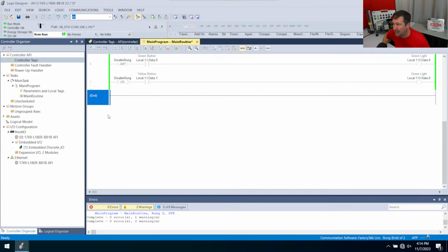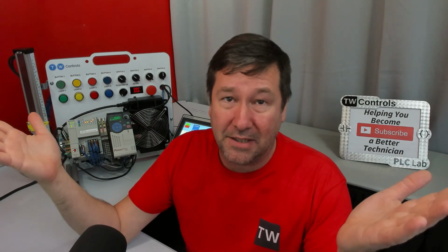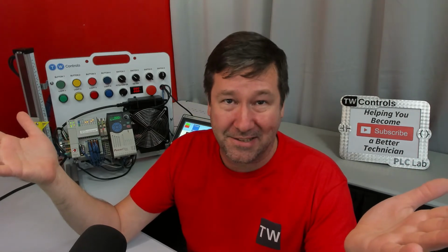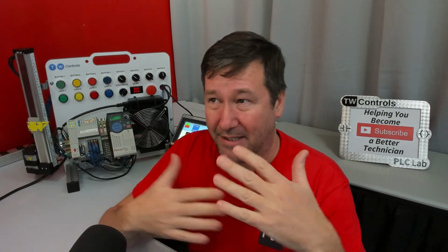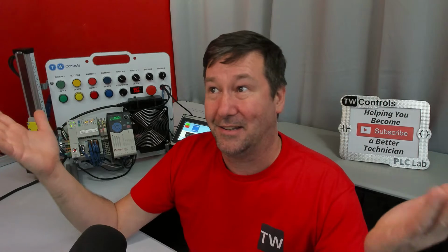Now, the other thing that a lot of you said that I really want to make sure we understand why is not a grand idea is, a lot of you said this is why you like to do your own test and have it all in one, because a lot of y'all are fixated on that it's still this duplicate destructive bit. And I've made two live streams in a week explaining that the AFI does make a rung false. It doesn't disable it. And a lot of you still believe it disables it, and the duplicate destructive bit causes the PLC to be erratic, and that's why Studio 5000 gives you that warning. I can't help you at this point.